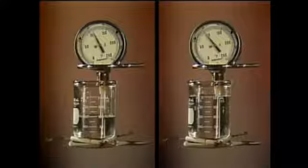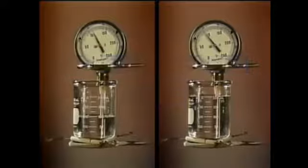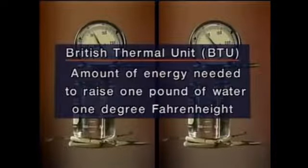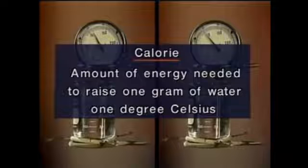The two units generally used to measure heat are the British Thermal Unit, or BTU, and the calorie. A BTU is the amount of energy needed to raise the temperature of 1 pound of water 1 degree Fahrenheit. A calorie is the amount of energy needed to raise the temperature of 1 gram of water 1 degree Celsius. Heat is a form of energy known as thermal energy. Thermal energy can be either stored in a substance or transferred from one substance to another. There's an important law of energy called the law of energy conservation. This law states that energy can be neither created nor destroyed, only altered in form.